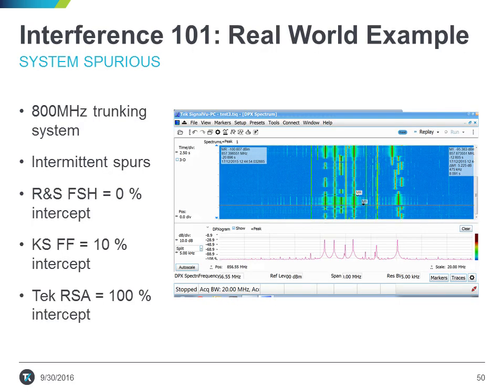This slide shows us a real-world example of using a real-time spectrum analyzer to determine when interference was actually happening. In this case, we were measuring the output of an antenna farm that had a spurious transmitter. The trouble with this spurious transmitter is that the factors that caused the spurious output were transient in nature, and the victim receiver was over 3 megahertz away.